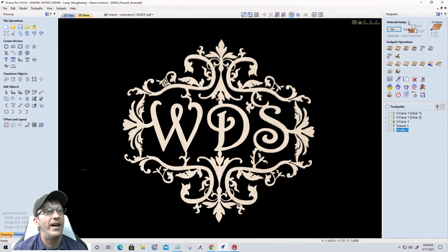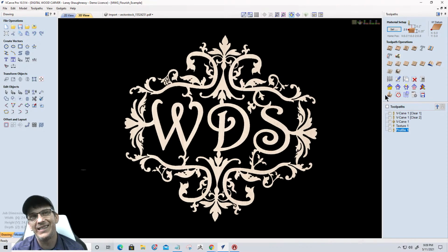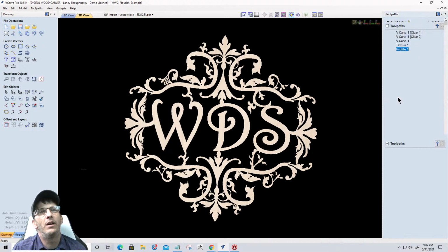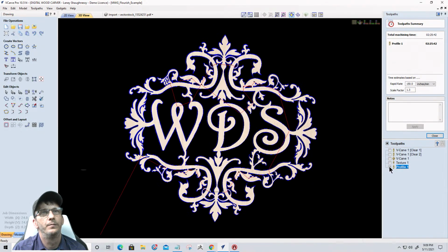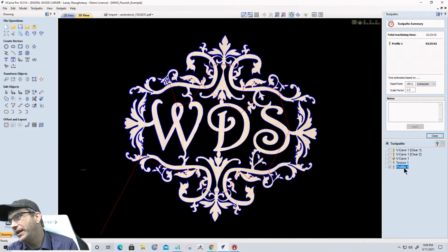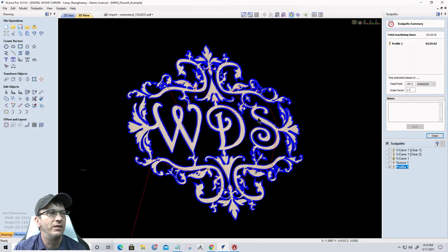This profile cut here, this simple little profile cut with a 1/16 inch end mill, because I wanted to be able to get into all those little nooks and crannies. We are looking at about a 2-hour 25-minute cut. So whoever said under 3 hours, Harvey on that one. So 2 hours 25 minutes for that 1/16 of an inch bit to go in there and cut that 1/4" material.